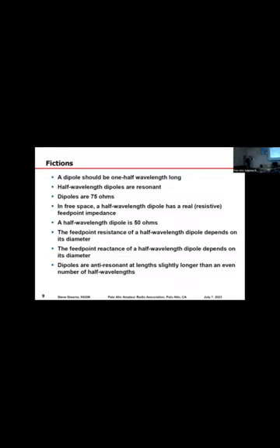In free space, a half wavelength dipole has a real resistive feed point impedance. A half wave dipole is 50 ohms. Wow, we went from 75 to 50. Is that even true? No. The feed point resistance of a half wavelength dipole depends on its diameter.